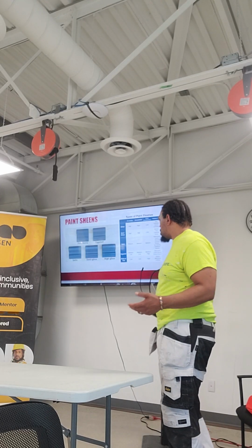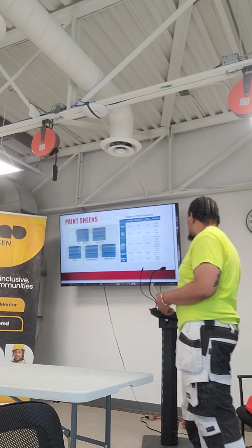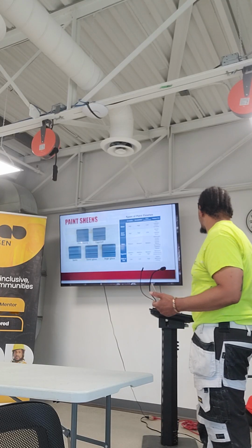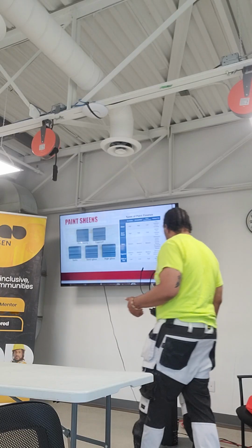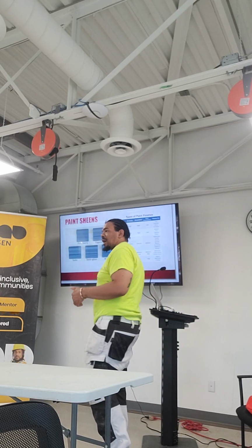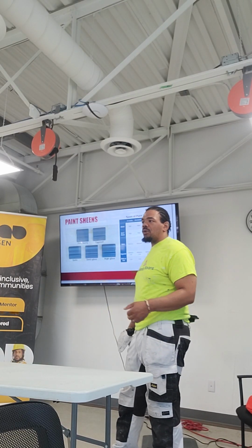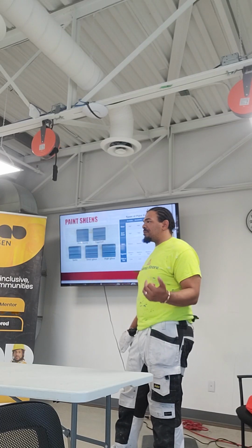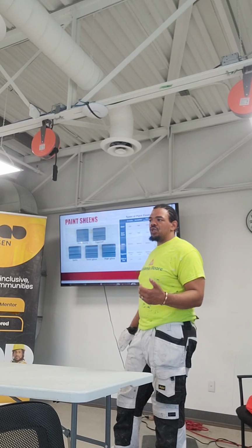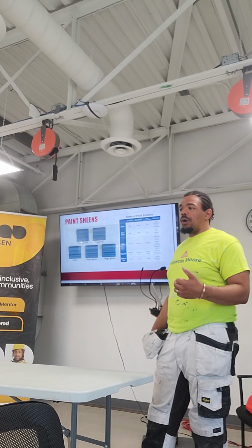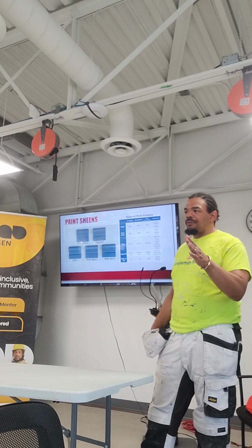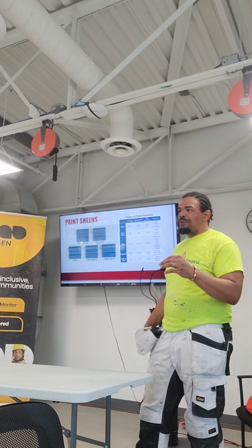So that's the paint that we're going to use. But then, again, you have all your sheens and you have all your different things that are used in different ways. And it's just important to understand the gloss levels and how things work correctly. So gloss level for semi-gloss, you want to use semi-gloss on trim and doors. You don't really want to use semi-gloss on walls unless the walls are pristine and perfect. Otherwise, any imperfection will show up.